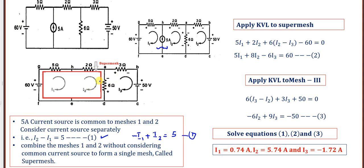And in the 6 ohms, while writing KVL for the super mesh, you have to consider the polarities: plus, minus, plus, minus. So plus 6 into I2 minus I3, and this is minus plus, so minus 60 is equal to 0. Simplify, and you'll get 5I1 plus 2I2 plus 6I2, that is 8I2, minus 6I3 is equal to 60. This 60 we bring to the right side. So equation number 2 is over.